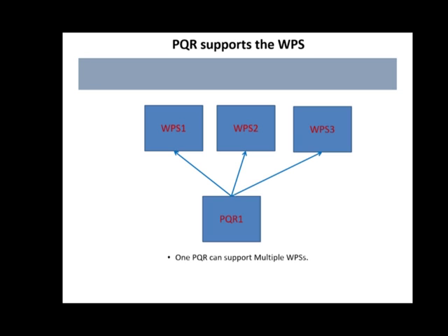customer number one, we're going to use WPS number one to make his component. Well, he only wants us to use 1/8 inch material, 1/8 inch 7018. Customer number two with WPS number two, he's like, I don't care. You can use 1/8 to 3/8.